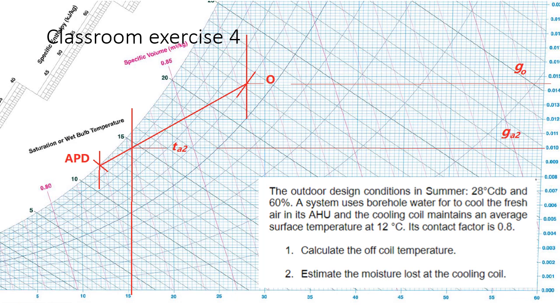Now imagine in this 28 degrees, 60% saturated, you take a can of beer out of the fridge, you immediately see the surface covered by droplets because the surface is much lower than 19 degrees, right? Anything lower than 19 degrees, you will see condensation. So the surface at 12 degrees surely will be covered by condensation, right?